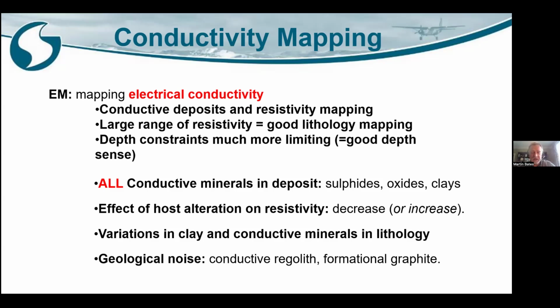So penetration of the signal is not just a function of the system, but also a function of the subsurface conductivity, how far down you can see. And in the EM world, especially in time domain, because we're creating the response, there are loads and loads of different systems out there with different characteristics, generating different shape pulses, sometimes alternating different pulses, sometimes cutting off really quickly, sometimes not, sometimes very high, strong signals, sometimes weaker. All with different strengths and weaknesses in terms of what they can see and what they can resolve in the subsurface.